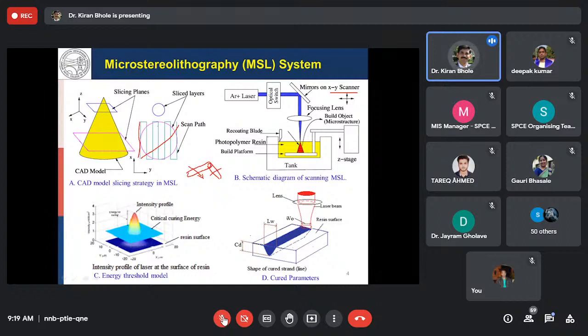The conventional straight line mechanism is going to have clearance in microns and hence error in microns, and this is the problem. The ideal line to be traced is this, but the actual line traced will be like this, and you will lose all the accuracy, and fabrication will not be possible. So what we require is a very accurate XY scanner which can give accuracy in nanometers. Then only will it be possible to fabricate components of micron size, right?